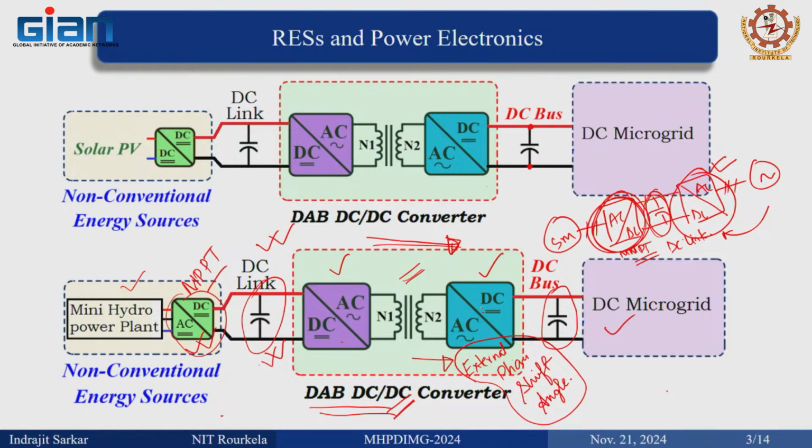But when you need to regulate this DC voltage, you will see you need to have a bidirectional power flow. As I already explained yesterday, when it is a DC-DC converter and it is going to maintain any DC bus voltage, it has to be bidirectional in nature, otherwise that cannot be achieved. Okay, is that clear?